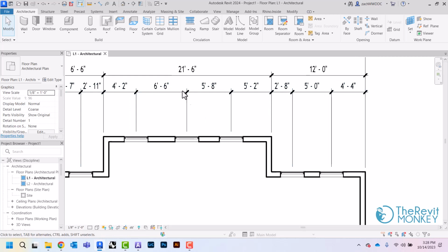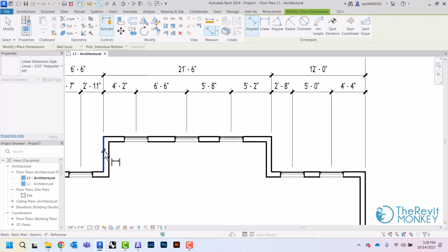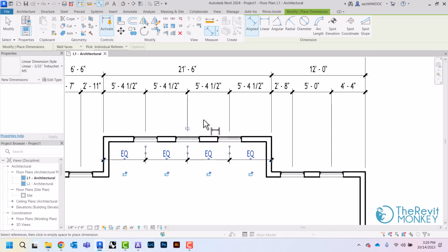So another thing that Revit allows us to do is, if I just take these 3 windows, for example, and I go like this, if I hit this EQ button right here, this will equally space them. Now, the problem with this is notice how there's a big area on the outside, but between the windows, it's a lot smaller.